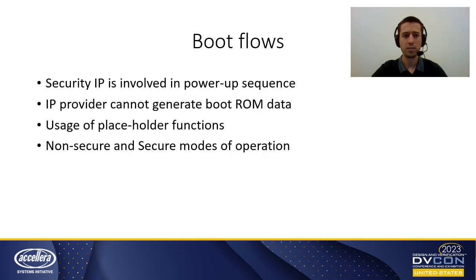We all know that when the SoC is powered on, the first thing it does is execute the power up sequence. The PMU unit is mostly responsible for this. What does it mean? It takes all blocks out of reset and provides clock to them in a certain order.